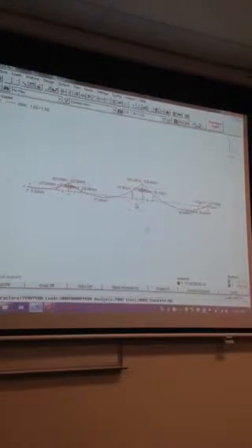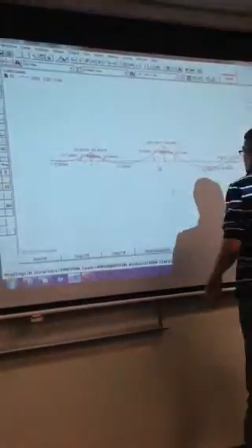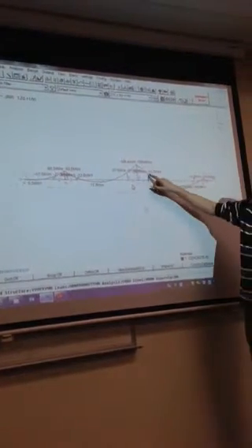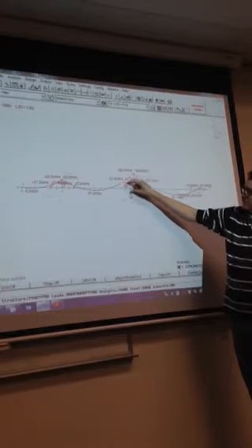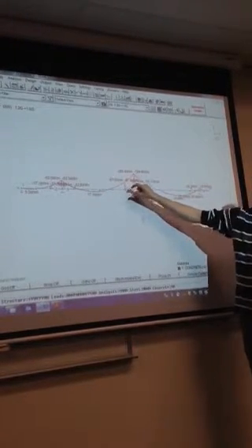Top, beautiful. So when we're looking at the maximum bending moment, which is at the middle of the support, this one here, 126, our effective depth is actually based on the depth of the beam. So we can actually increase our effective depth, but we'd also need to check it at these two locations. You pick the maximum, so in this case it's 57.6, and our effective depth is then just based on the slab depth, minus cover, minus half the bar.